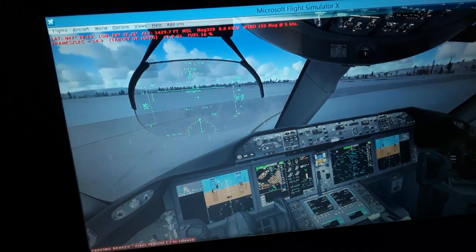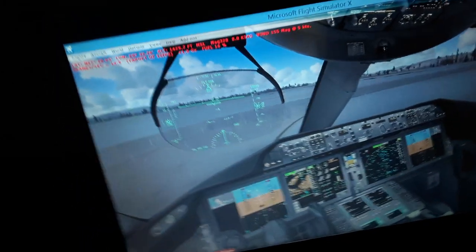That displays the airspeed indicated, the airspeed selected from the autopilot, the flight director system panel, the ground speed, the radio altitude above the ground level, the barometric altitude above the sea level, the target altitude selected from the autopilot and flight director system panel, the barometric pressure of the outside atmosphere, the radio altitude selected also, and the minimum altitude, and also the altitude indicator, the pitch ladder decrease, the bank angle increase, the artificial horizon.